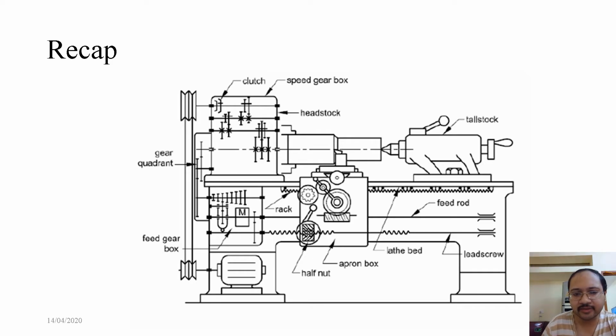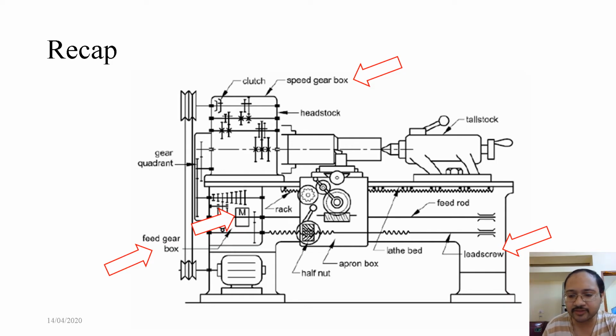Before we discuss the method of changing speeds and feeds in a lathe, let us recall the working principle of the speed gearbox, feed gearbox, meander, and the thread cutting mechanisms in brief. Speed gearbox involving the sliding cluster or clutches helps to change the speed and provide suitable spindle torque relevant to that speed. The feed gearbox, with the help of a Norton and meander drive arrangement, helps to feed the tool post in the longitudinal or the transverse direction as required for the machining operation.